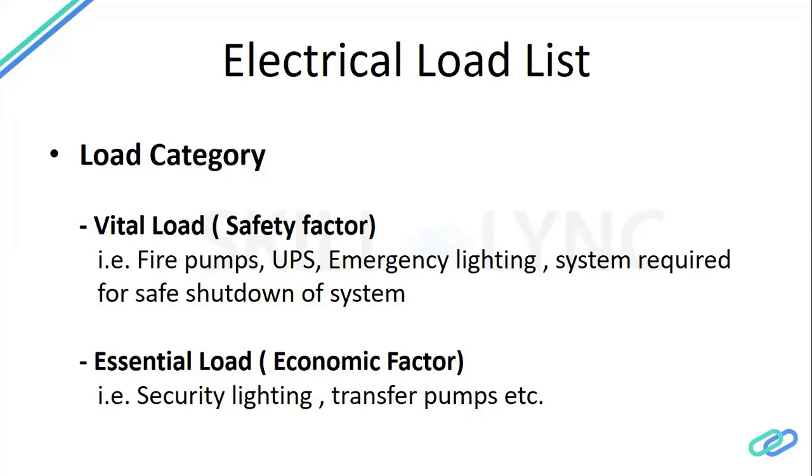Next is the essential load. You can see the economic factor. Some loads are necessary for economic purposes. Like in the night, you need security lighting. You need to operate transfer pumps because your plant is running and suddenly a shutdown happens, but your product is already ready. So you want to transfer the product to a safe place so you will not lose money. That's why some loads are necessary from the economic point of view.